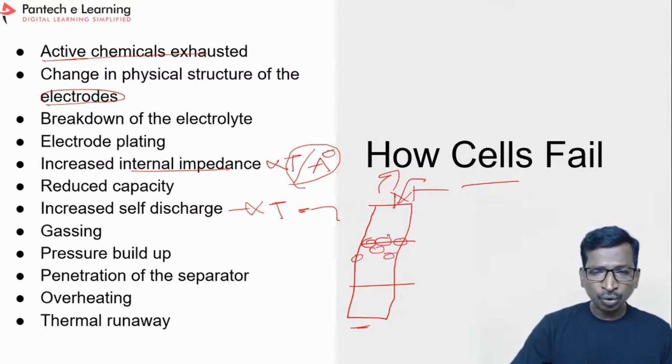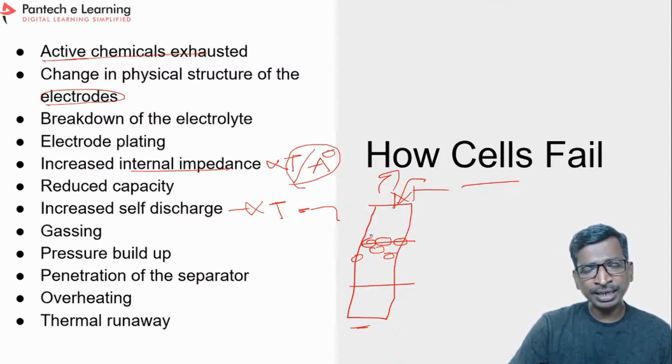While charging as well as discharging, bubbles will be created. If there are huge variations in the temperature and chemical process, then the bubble size may increase. So we have to arrest these bubbles by maintaining the cell temperature.